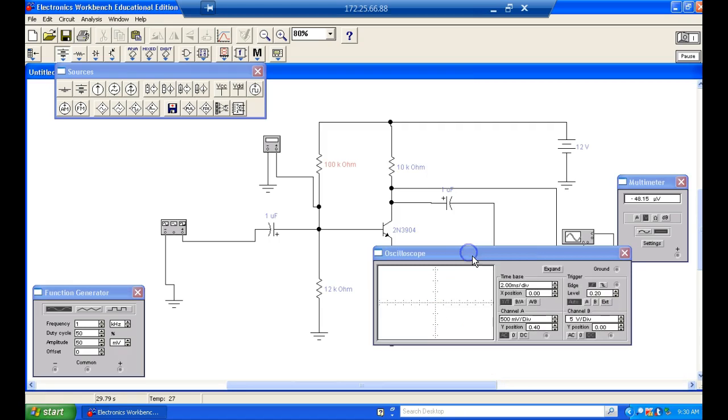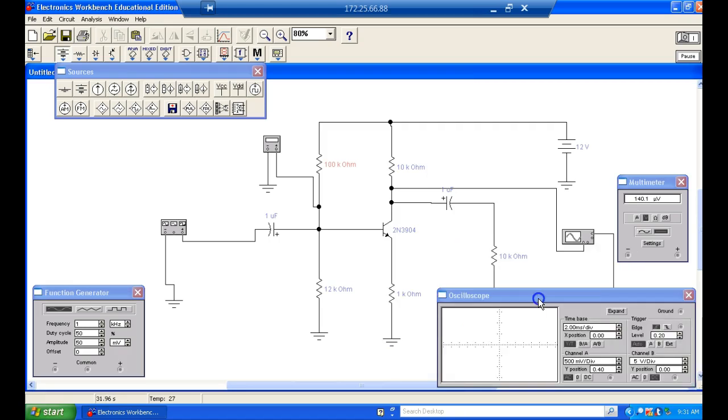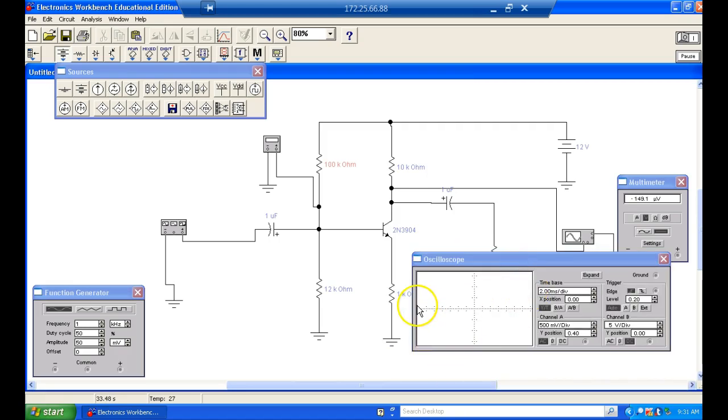Nothing. But guys, we have a bad tendency, if we don't see anything, of trying to see something. They'll come over to this oscilloscope and just start turning it down, and eventually you're going to see something, because AC will couple through. We had a big problem with people when we used to teach computer troubleshooting. They would turn their scope down until they saw something. And eventually, in an AC circuit, you're going to see something, right?